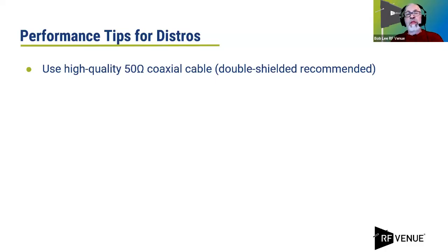Now, foil does a very good job of encircling that inner conductor, but foil has relatively high resistance. Another type of shield is braid, copper braid. Now, copper braid has very low resistance, but it has gaps in it, especially if you bend it.